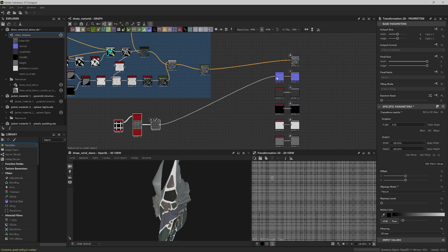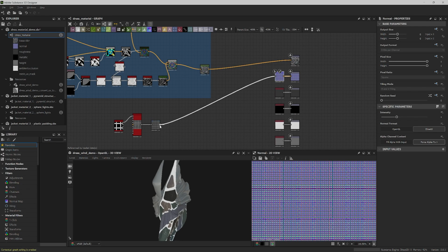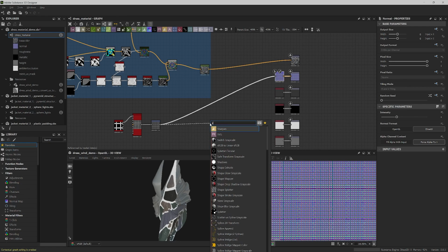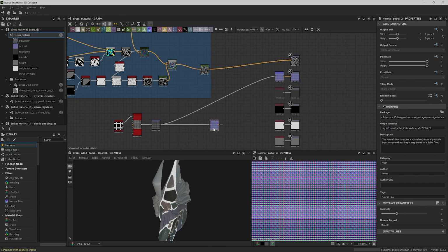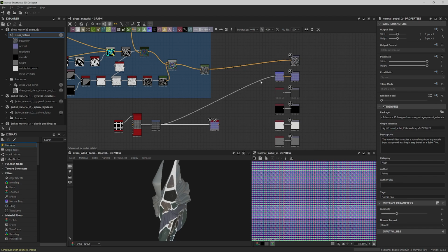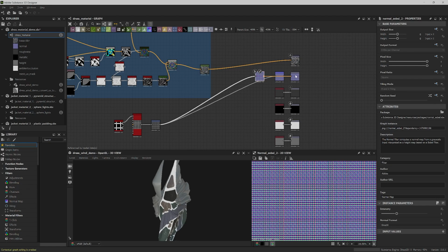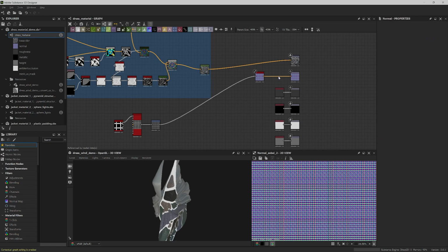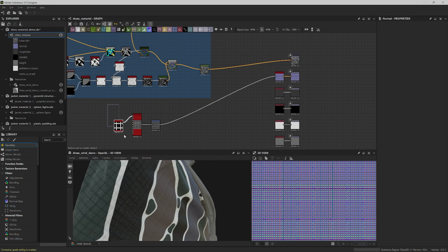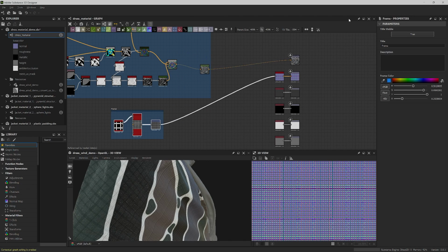Next, take this into the normal map. A Sobel normal is sometimes preferable for materials like fabrics, as it filters more than the standard normal, giving you a more gentle effect. You can notice the difference here. The usual normal appears a bit harsh. Let's go with the Sobel for this one. Select the weave nodes, frame them, and label this section normal.